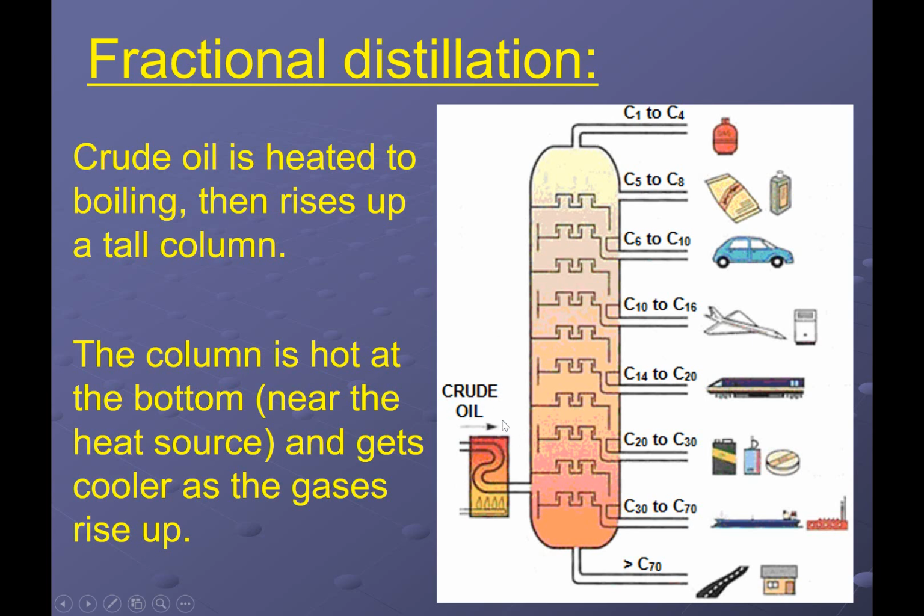Now all that big mixture, now they're all gases, they get shunted through this distillation column. And we know from our London forces, when we think about hydrocarbons, although carbon does have a slight win over hydrogen in electronegativity, it's not big enough to be a polar compound. We always say hydrocarbons are nonpolar. They rely on those London forces, those background attractions between temporary and instantaneous dipoles. We know that London forces are stronger the more charges we have, indicated by the size of the molecule.